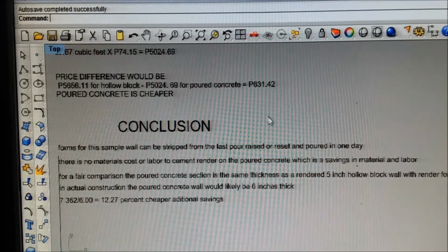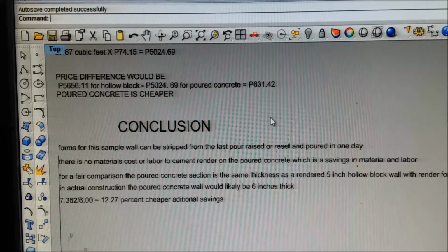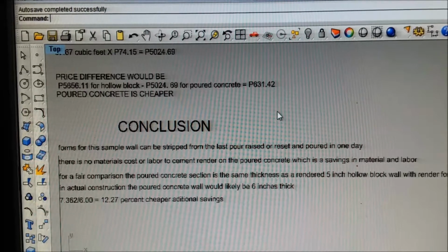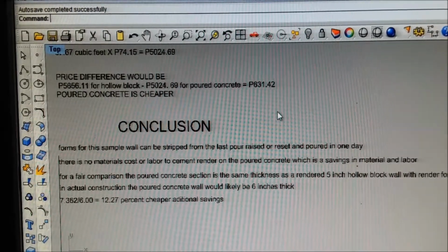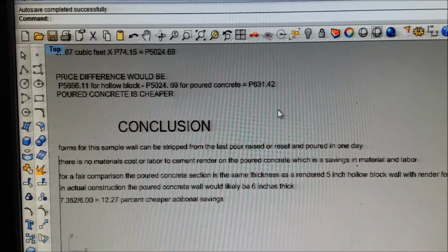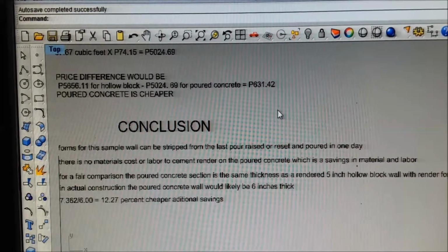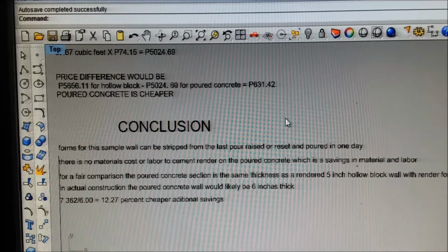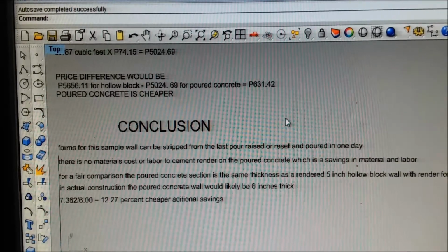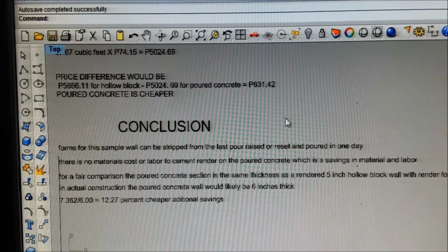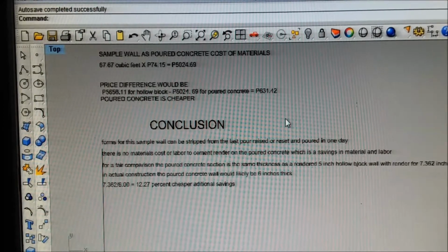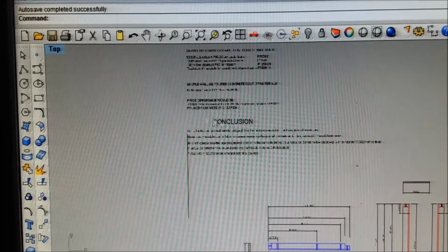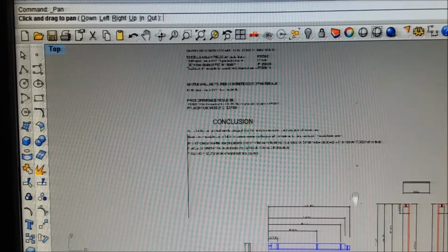If you are doing a one-story building and you were putting the made-in-place angle iron metal trusses or metal substructure for a steel roof, there's no need for a top beam on poured concrete. If it makes you feel better, you can pour a top beam all over the whole thing like they do with hollow block. As long as you are structurally sound, you can build anything you want over here, best I can tell. It needs to look like your building permit drawings. That's liable to cause you problems.